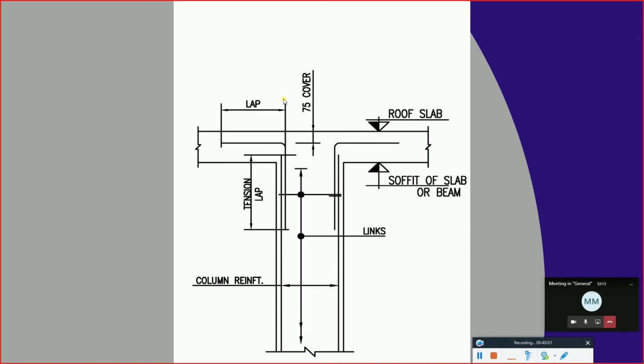Now, if you don't have that particular reinforcement, if you didn't do it like this case, and I want to make a connection between the new column of the new floor and the existing final floor, what we normally do is drilling. So we drill, we bore the existing concrete or column, but carefully, so you will not cut the reinforcement, and then you will insert your new reinforcement. Why are we doing that? To ensure that the first column is connected to the other column.